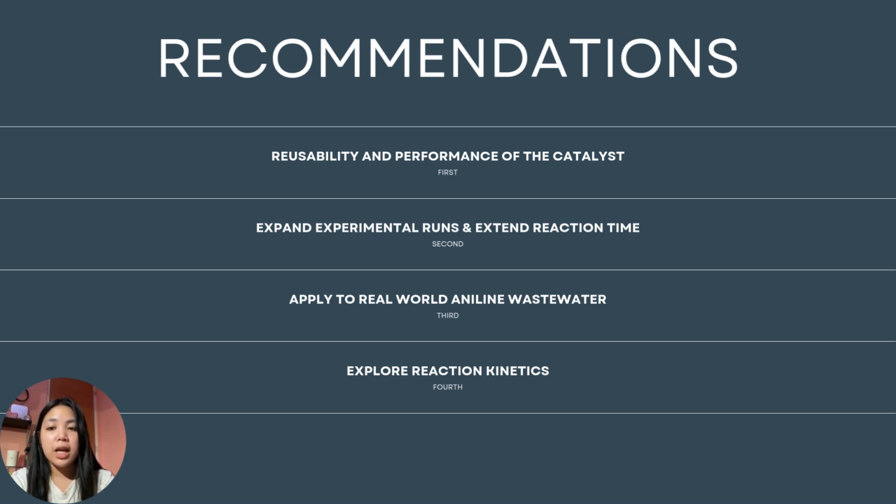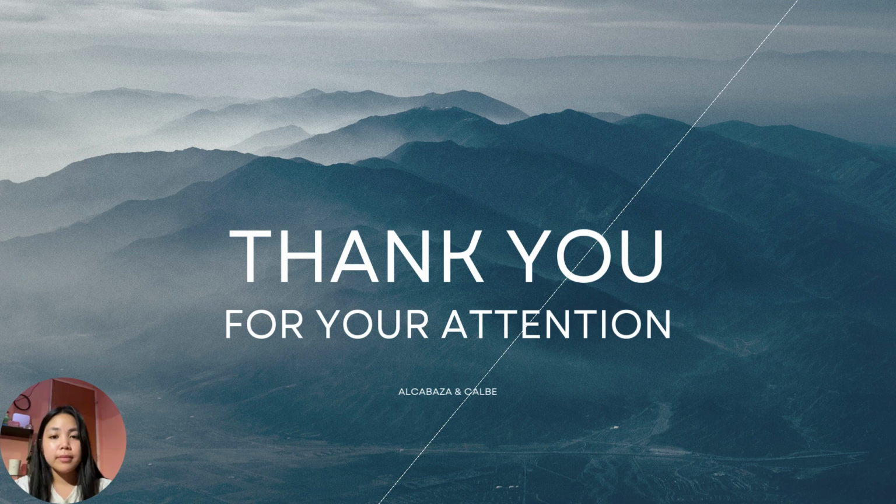Finally, conducting a kinetic analysis would allow better prediction of degradation rates and support reactor design. Including other variables like temperature, UV intensity, and mixing rate could also improve the model's accuracy and make it more applicable to real-world conditions. Overall, our study demonstrates that FeCHI-04 at CSBC is a promising and sustainable catalyst for degrading aniline in wastewater through the heterogeneous photo-Fenton process. While there's still room to optimize and expand the system, this research provides a strong foundation for developing more effective and practical water treatment solutions in the future.